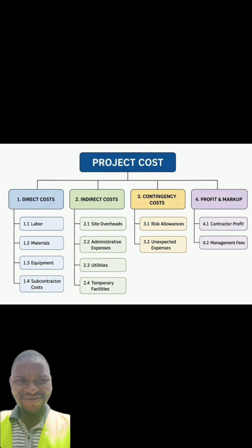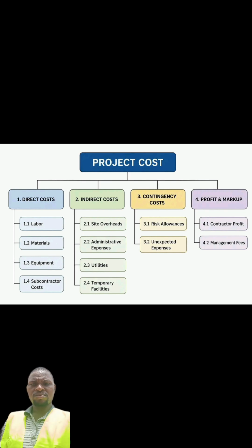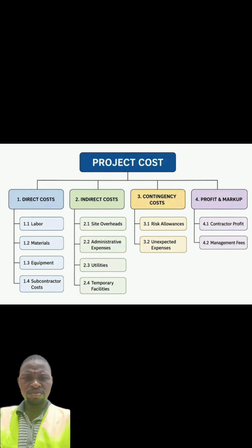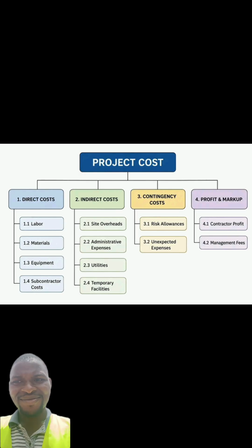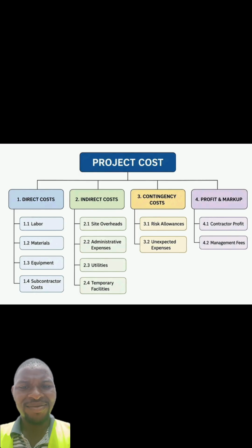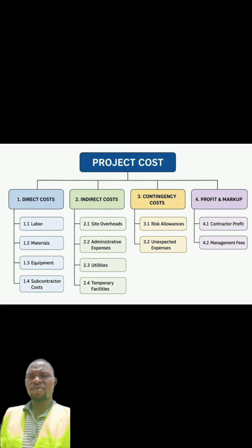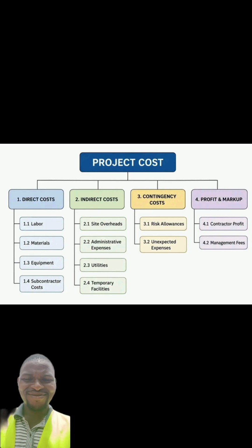The next point we have is temporary facilities. This could be your toilet on site, your site office, which some people usually use a container for, or maybe some temporary structures. All these temporary facilities are not part of the construction itself or the structure, but they only help to facilitate the construction procedure on ground.